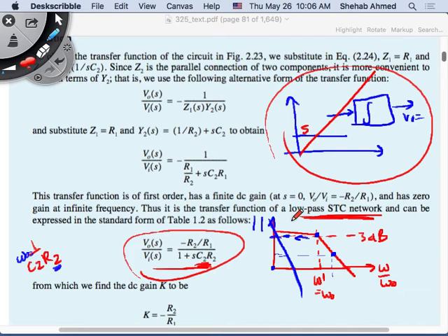So that's why we have bands, and that's why we don't use DC. That's why we use AC. That's why integrators are not good with DC circuits. Developing an integrator for a DC input is a problem, because the gain for any DC input will be infinity, and that will saturate. At infinity, it will saturate to something after some point in time. In a non-inverting configuration, it will saturate to the positive value. If it's inverting, it will saturate to the negative value.